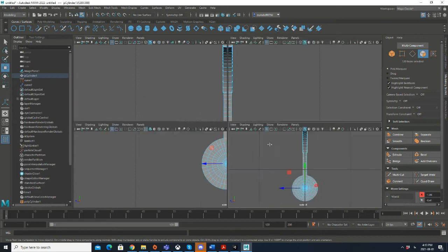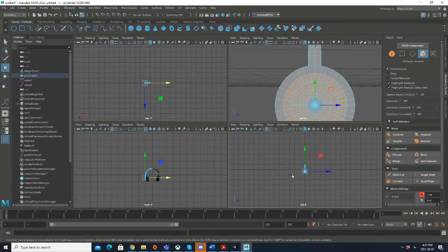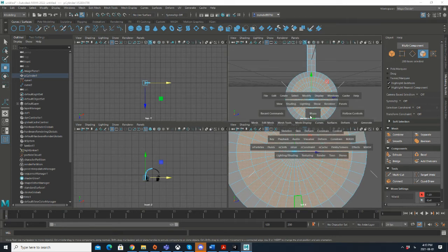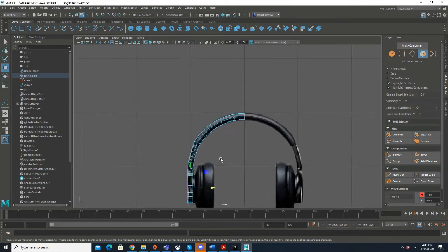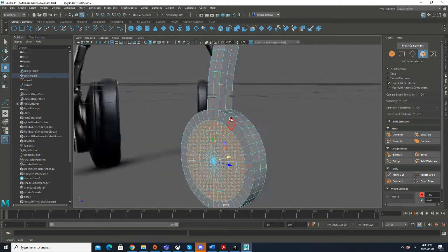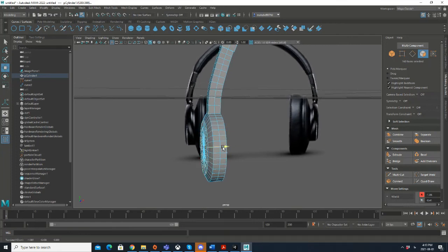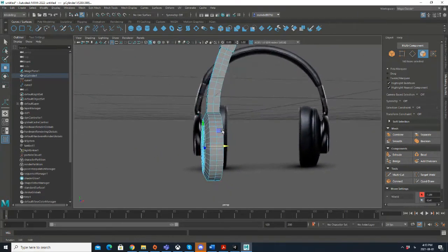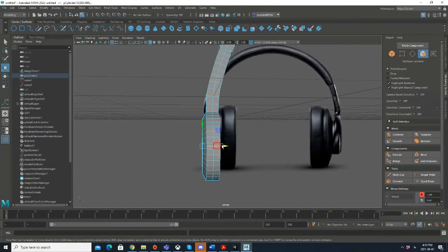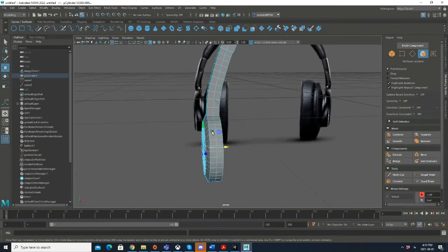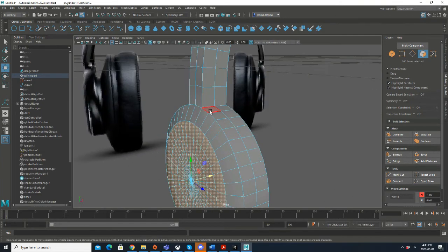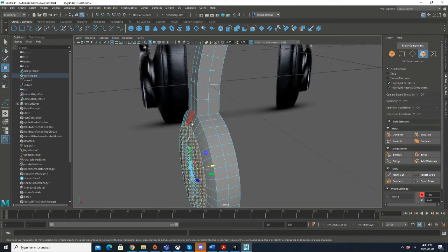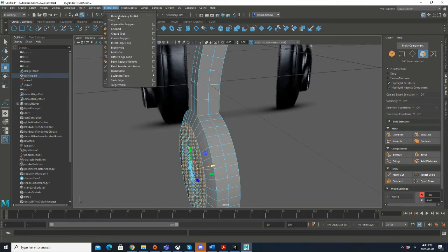So what I'm going to do is to take a look at the left view. Select all these faces. I should go here and deselect the faces from this part, and you can either extrude these faces, or for this particular part here, I would just move these faces a little left. The reason I'm saying that is you may need to have an edge here or not, based on what you are thinking for your model.